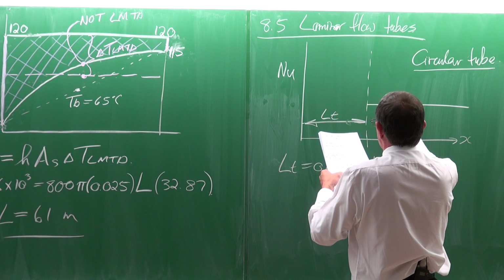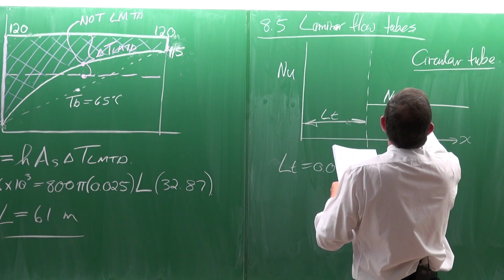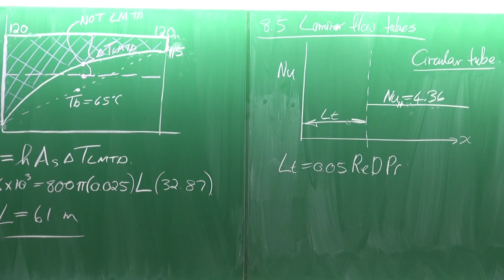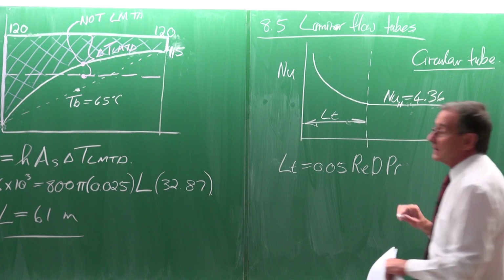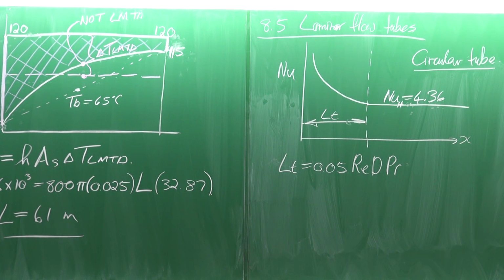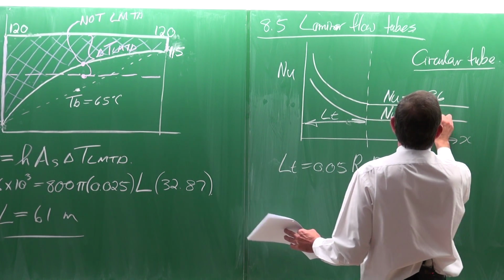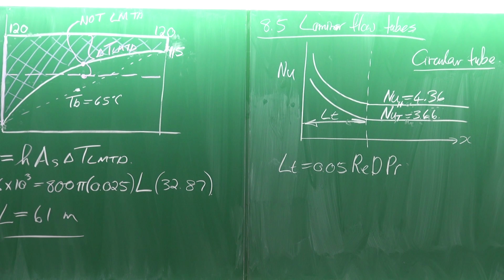And it says that the Nusselt number is equal to 4.36. And that is the H case. So it's for the constant heat flux case. Okay. So the Nusselt number for laminar flow, fully developed, is 4.36. And anybody who passed heat transfer will tell you that. So it's an important number to remember, if you want to remember it. Okay. Then, not given in the textbook, but that derivation is also available in literature. You can go and also derive it for a constant wall temperature. So for constant wall temperature, the Nusselt number is equal to 3.66. Remember, for fully developed flow.